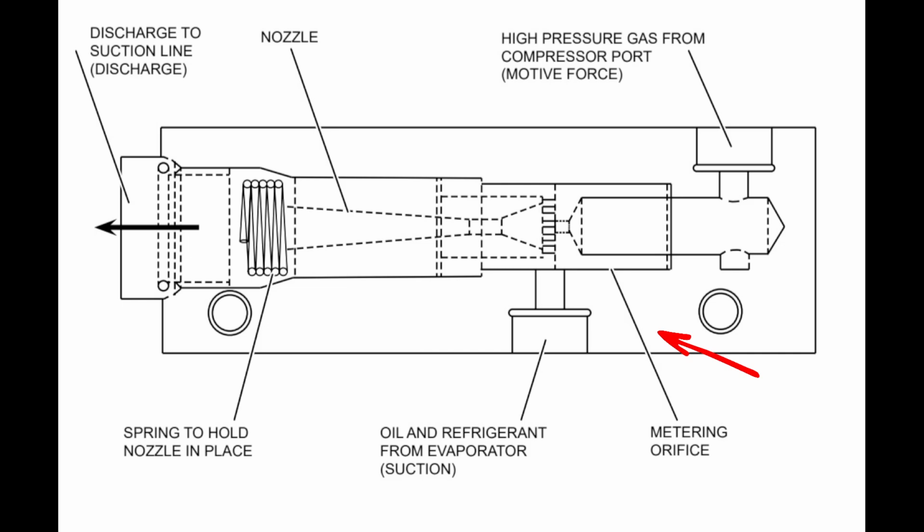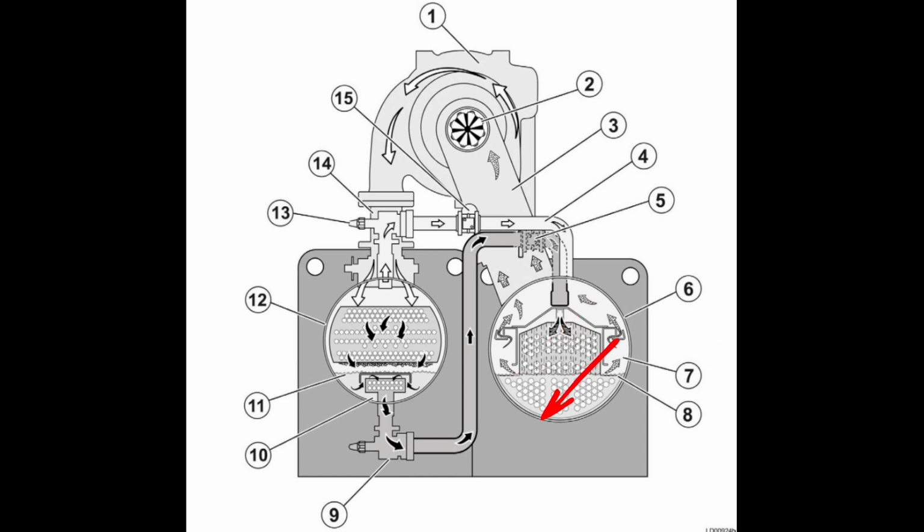Yeah. And that's one reason why on some of these evaporators, you'll see some of these eductor ports are very low down towards the bottom of the evaporator. Not all of them, but some of them. And that goes back to, typically when I see that, they're usually the hybrid style or design. One example, and that's not using an eductor, is an RTHD. That's a hybrid falling film evaporator, but it actually has its oil recovery system using a gas pump. So it's a different style of recovery, but it's right at the bottom of the barrel.